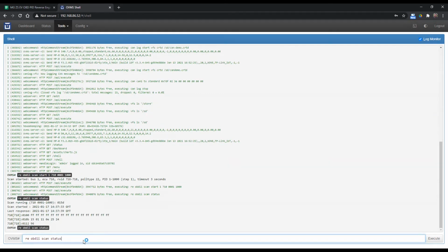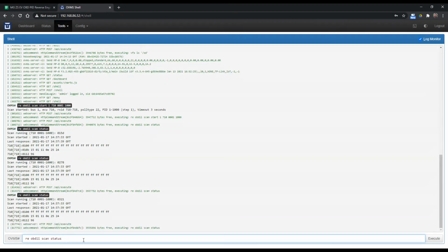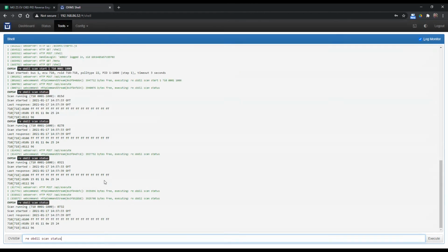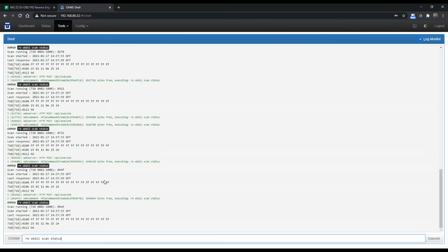And you can see here it's collecting a lot of data from the car. So we're up to 100 and something, probably. And there you go, 321. Tells you where we are. So this will run quite nicely in the background, and we'll be scanning all of the data from that ECU. And when it completes, it's almost there, it's at 700 now. When it completes, what we get is a very nice list of all the PIDs and all the responded data.